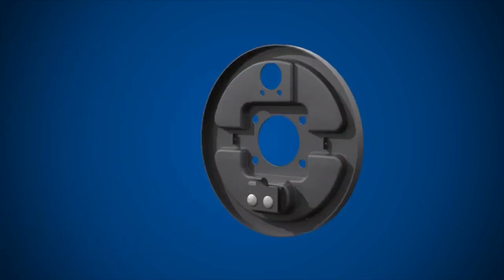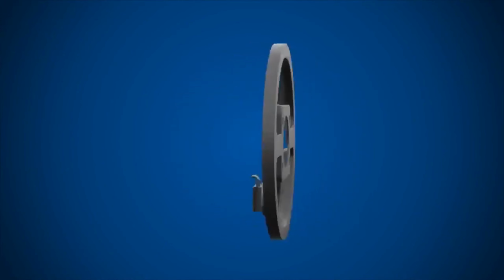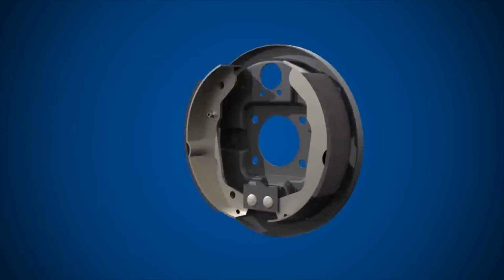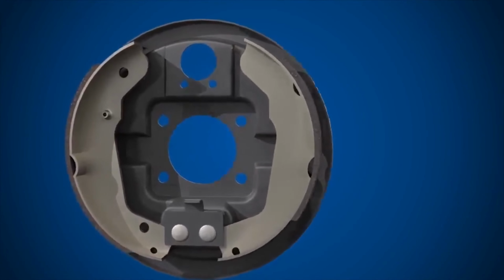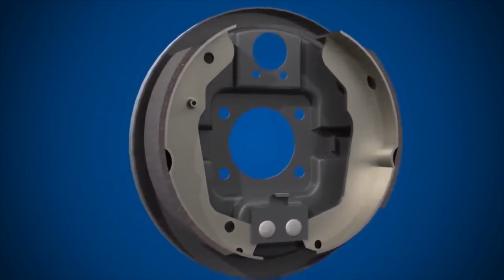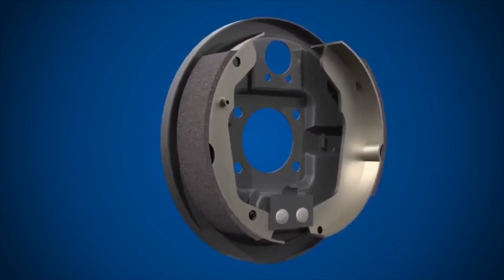The backplate remains stationary and provides a fixed base for the other components to attach. Next, we have the brake shoes. Brake shoes consist of a steel frame fitted with friction material or brake lining. This material is bonded or riveted to the outer face of the shoe frame. There is a wheel cylinder.